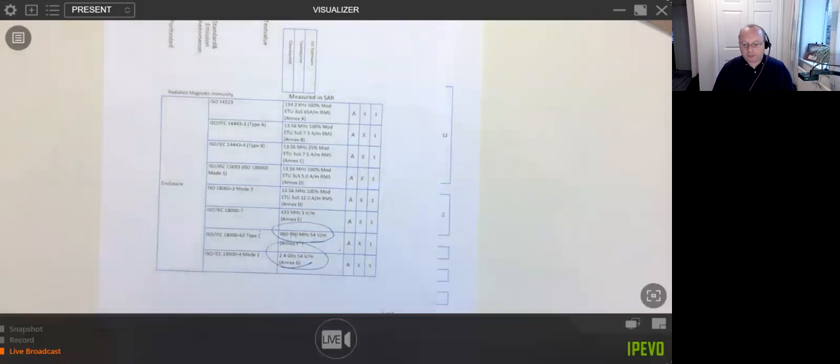So yeah, radio immunity for medical devices, it's a very tough cookie. It's not easy to do. I think we just had to do 2 spins of this board, and the only reason we had to do 2 spins really was to tidy up all the tracking. So all the tracks are nice and straight, without too many kinks in. If you're doing auto route, it's very easy to end up with kinks in your design. So I got rid of all the kinks. Everything's nice and compact. And yeah, it was a thing of beauty.